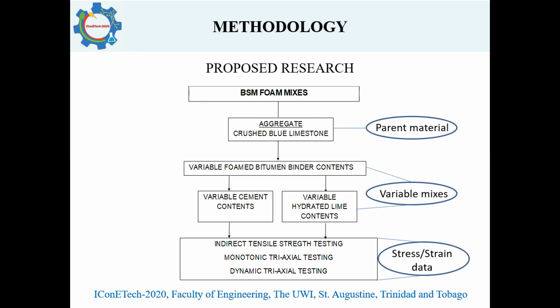The study proposes to investigate the laboratory performance of 4 bitumen stabilized crushed mixes of varying combinations of 4 bitumen contents, active filler type, 2 in fact, of cement and hydrated lime, and variable active filler contents. Triaxial testing is to be carried out to provide stress strain data for determining shear strain accumulation of the material and dissipated energy data.